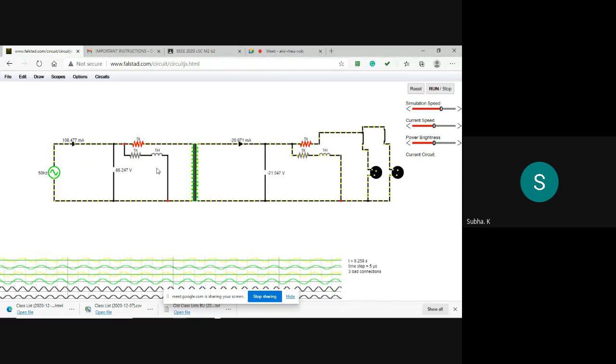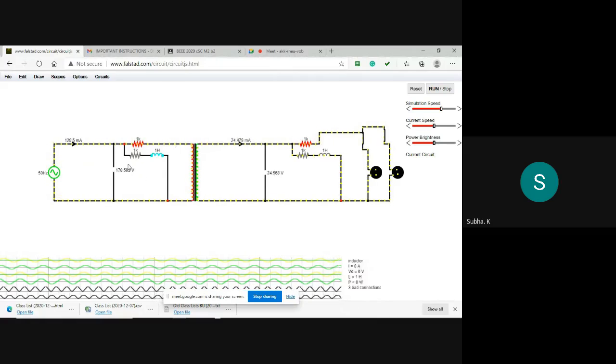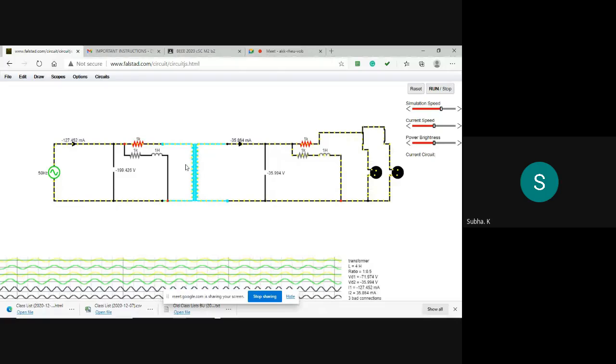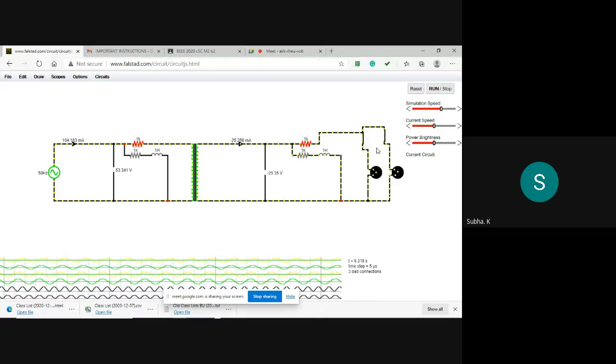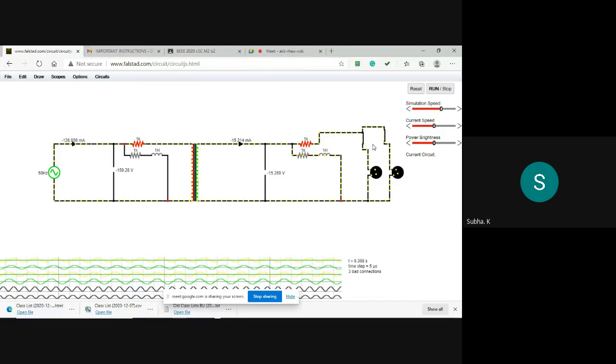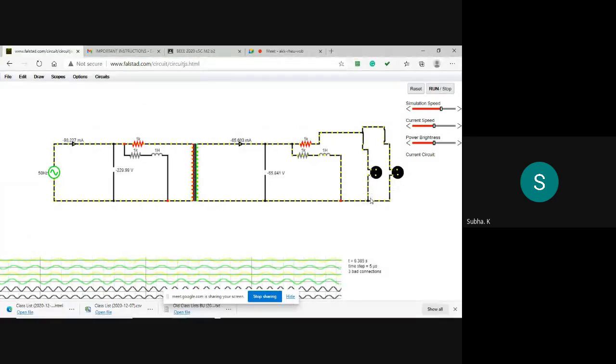And there is no wattmeter, so I am trying to realize a wattmeter by using the current coil and pressure coil in combination. Okay, this way you can try it out. Roughly you take readings. It may not be accurate. And lamp loads I am giving. First you have to take the no load reading.